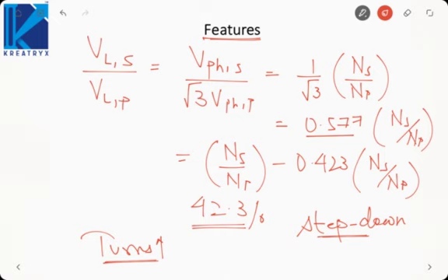And the last thing is that since the secondary is delta connected, delta winding will allow the flow of third harmonic magnetizing current, due to which EMF and flux will be sinusoidal. Remember, whenever there is a delta connected winding, either primary, secondary or tertiary, it will always keep the EMF sinusoidal. So ideal case is that either one of the windings should be delta connected. In any transformer connection, if one of the windings is delta, it will allow the flow of third harmonic magnetizing current. So that is the features of the star-delta type of transformer.